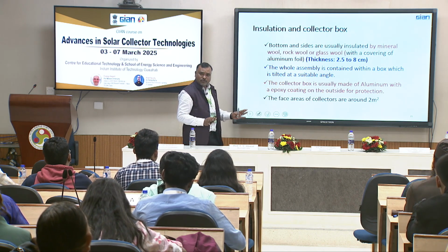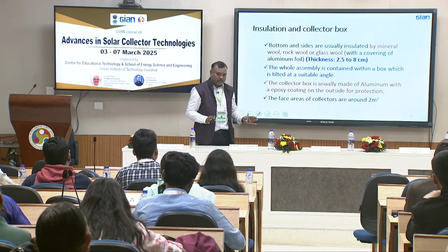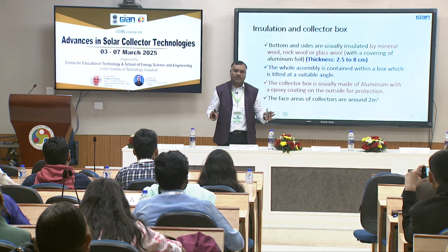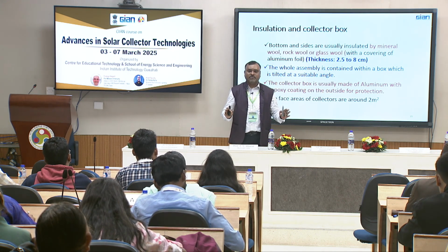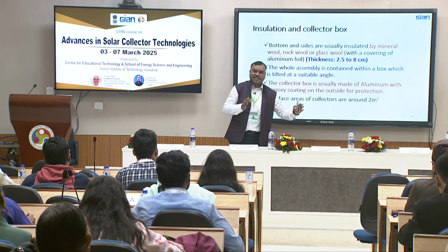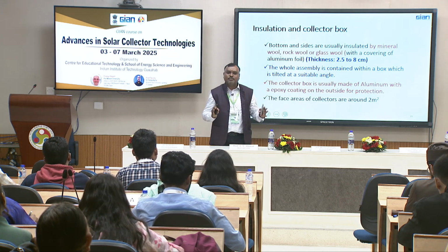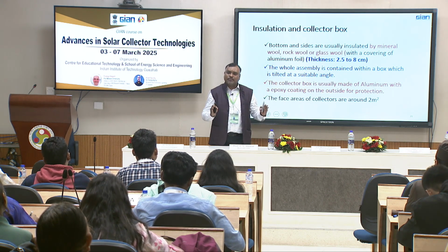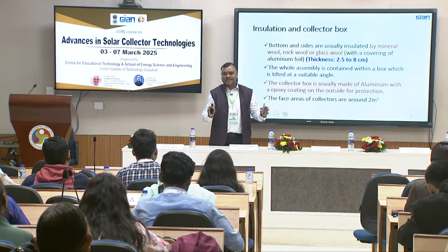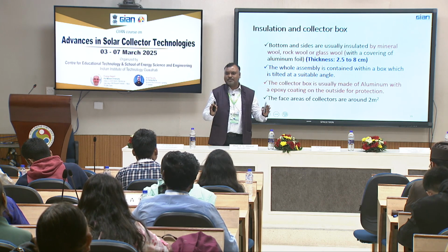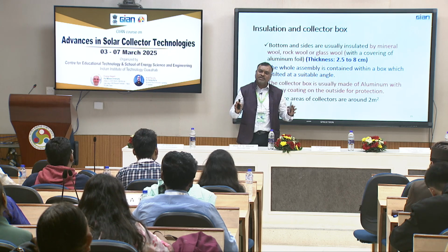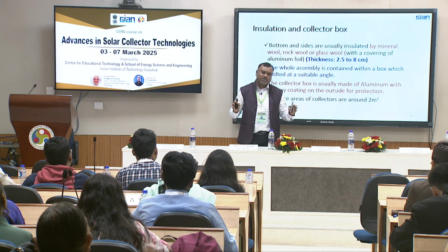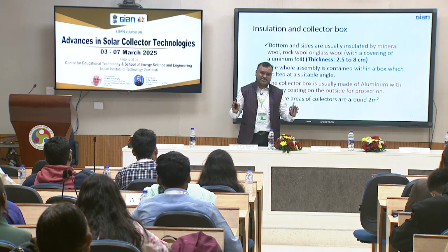So tilt angle, normally, depends on your requirements. Say for example you are devising a flat plate collector for a place like Meghalaya, maybe Shillong, or a place like Gujarat, or a place like Paris, okay, then what could be your concern? First thing, for which purpose you are installing. Say if you are designing this flat plate collector for Paris, your target should be why you are installing it, because in winter you are going to get some kind of thermal energy, okay.